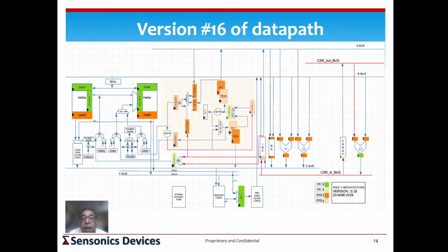On the right side, there is an ALU. That ALU is intended for CSR instructions. If you examine the instructions, you'll realize that either you route it through the integer ALU, or you have a separate bus for doing that. If you put it into the integer ALU, you lose a lot of cycles. Here you can save some cycles. So many iterations go on that.